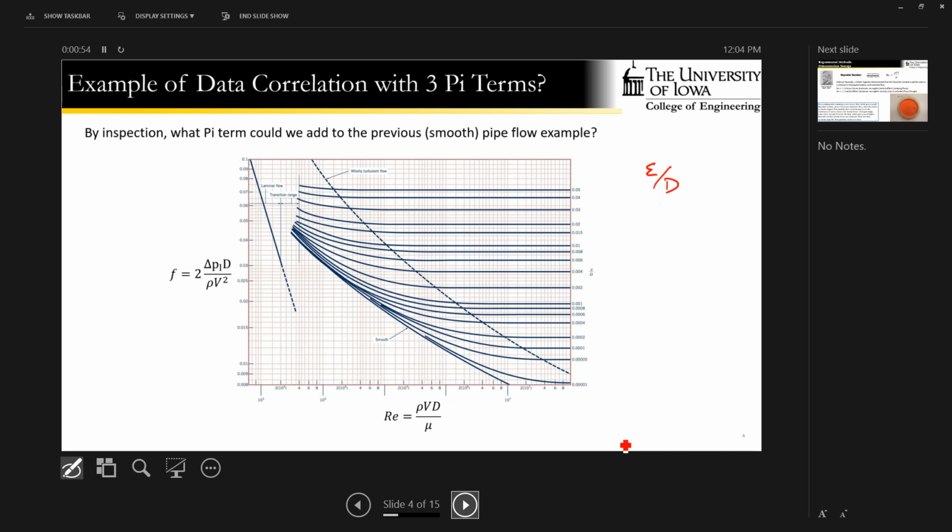And so what we get in that case is just like I kind of sketched on the last slide. We'll get our 2D axes, right? Reynolds number, pressure drop coefficients, and then we get a set of curves that correspond to different values of this dimensionless roughness. And so it's just a way of projecting this three-dimensional relationship onto a 2D set of axes.